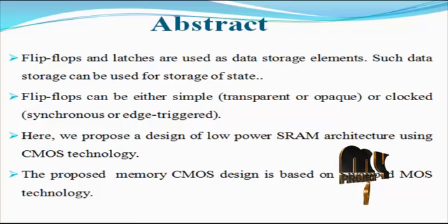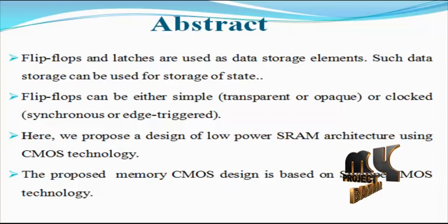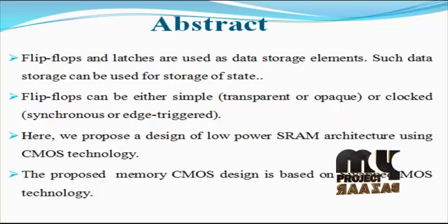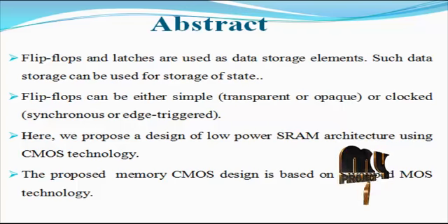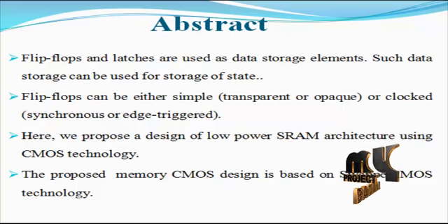SRAM is a form of semiconductor memory widely used in electronics, microprocessors and general computing applications. This form of semiconductor memory gained its name from the fact that data is held in a static function and does not need to be dynamically updated as in the case of DRAM memory. While the data in SRAM memory does not need to be refreshed dynamically, it is still volatile, meaning that when the power is removed from the memory device, the data is not held and will disappear. The operation of the SRAM memory cell is relatively straightforward.